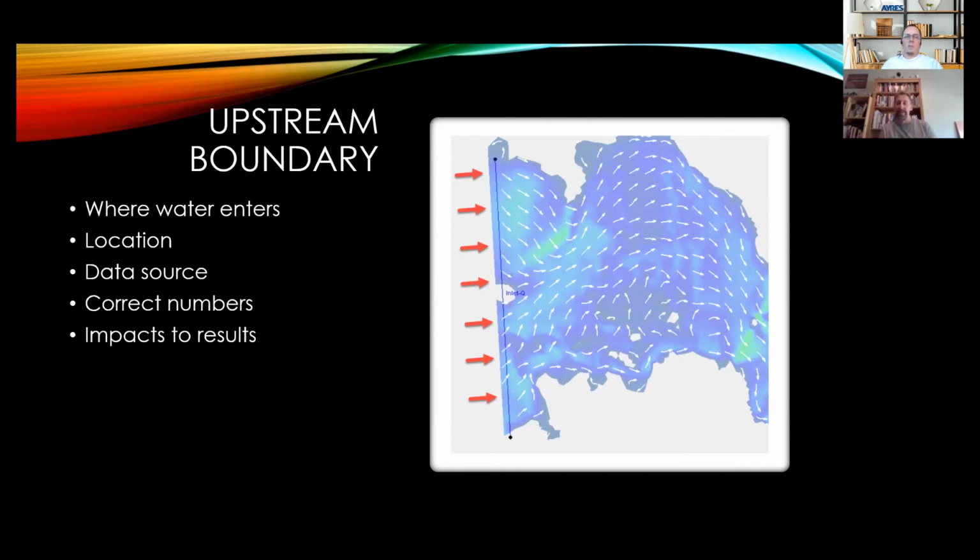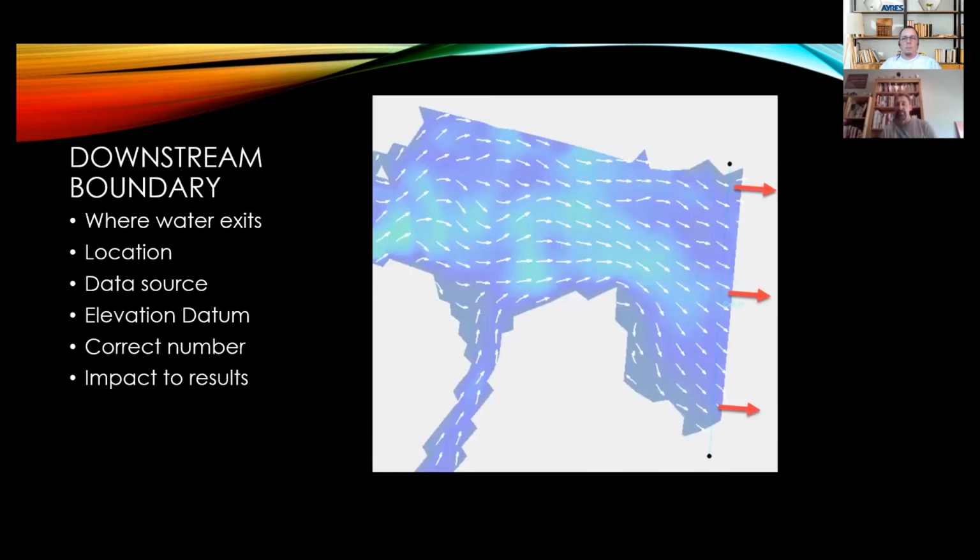Similar to 1D space, we need to be sure that our upstream boundary condition is located far enough upstream from our area of interest. In 2D space, we've seen all kinds of scenarios. We've seen the flow injected on the side of a bluff. We've seen convergence issues caused by too coarse or too fine of element spacing. The same with downstream boundary conditions. We've found that the orientation of elements at the downstream can also be the source of instabilities.